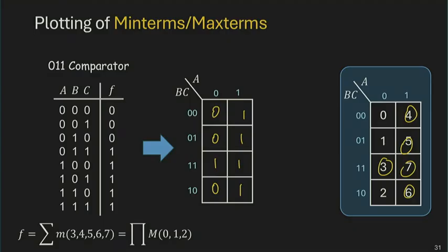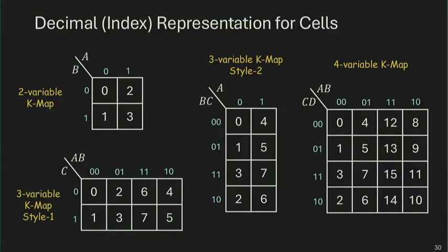If you go to more than 4 elements in your row or column space, then you don't get to have all the neighbors sitting next to each other. You almost have to fold this by half in this way, fold it by half in the other way, to have multiple foldings to visually appreciate this neighboring relationship. That's the reason why when we talk about Karnaugh maps, we usually just stop at the 4x4 Karnaugh map, where every cell has 4 neighbors, and they can go top, bottom, left, and right to visually see those 4 neighbors. At the edge, top, down, left, and wrap around right.